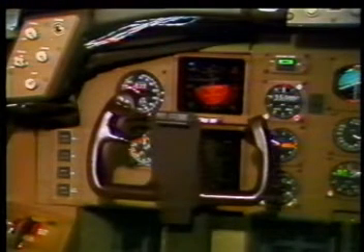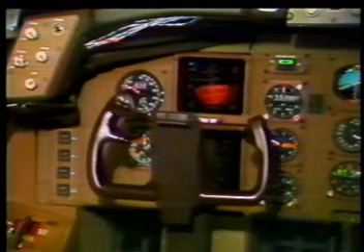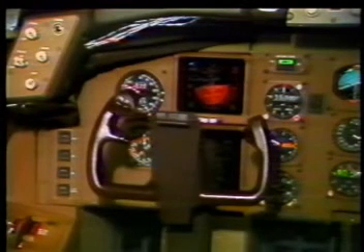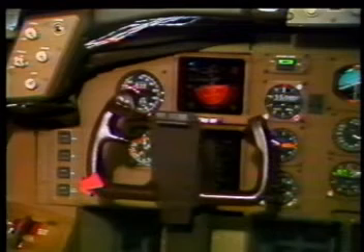The primary electronic air data instruments on the flight deck are located on the P1 and P3 panels. These are the pilot's altimeters and Mach airspeed indicators. Also located on these panels are the air data switches. These switches allow either pilot to select output data from either air data computer.